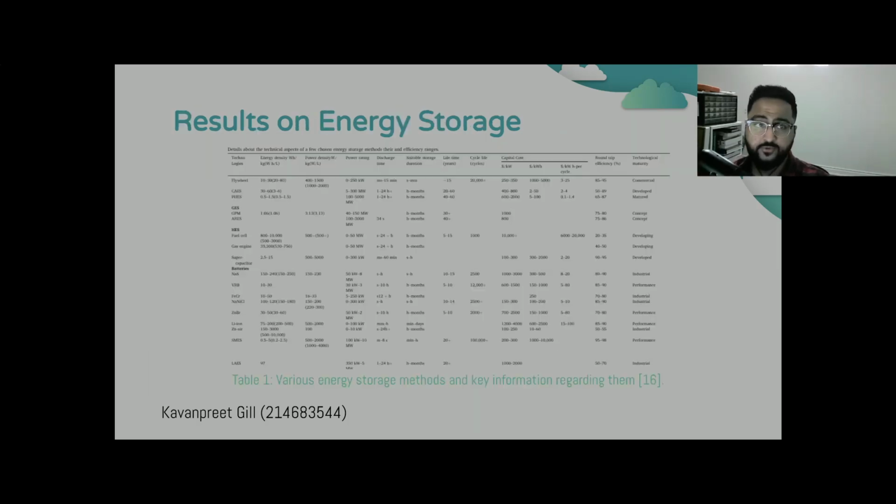This table compares 6 energy storage technologies. We'll only focus on a few key ones. Technologies like pumped hydro and flywheels are most common today. Flywheels offer high efficiency and fast response time, while pumped hydro scales to thousands of megawatts at very low cost per kilowatt hour.